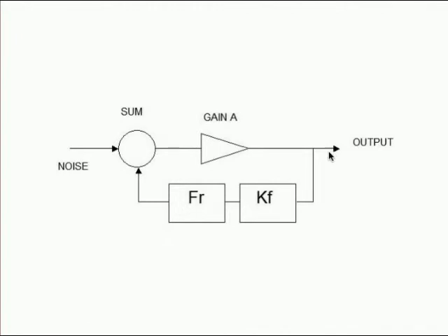So we have a massive gain. Really, this positive feedback is in effect increasing the gain of the amplifier, and so we can see that the effect of the positive feedback is going to have a massive effect on the bandwidth. It's going to vastly reduce the bandwidth.